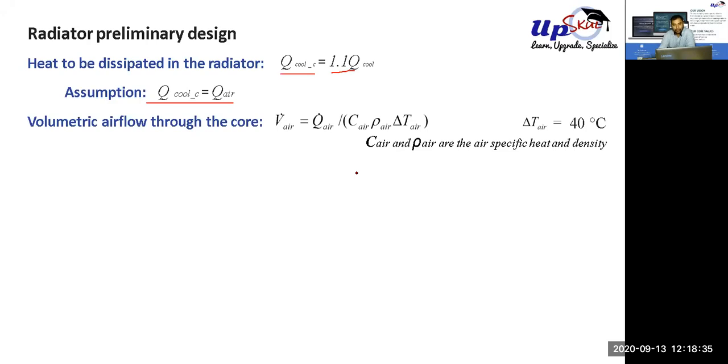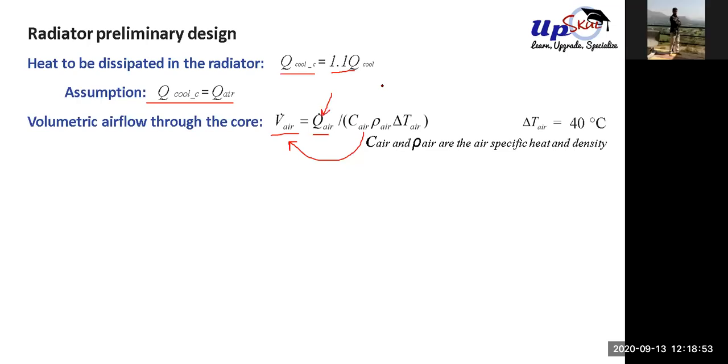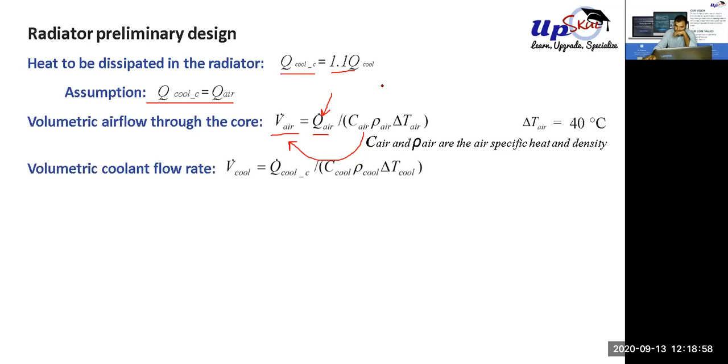So we calculate it based on the vehicle speed, or maybe in this case the flow rate. This is the vehicle speed, so this will actually come on the other side, and we are actually calculating this q. Next we need to know the volumetric coolant flow rate. That's comparatively easy. We just have the coolant flow rate data from the pump.